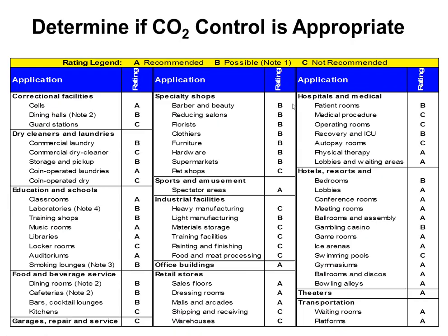All right, so this chart on this page is really useful. I've been using it for, I don't even know, 15 years. It does a really good job of illustrating what systems this is a good idea on. This is for demand control ventilation specifically with CO2 sensors. There are other forms of DCV, but this is a chart specifically for CO2 sensors. So what this chart means is if it's an A, it's a good idea. If it's a C, it's a bad idea. If it's a B, we probably need to talk about it.